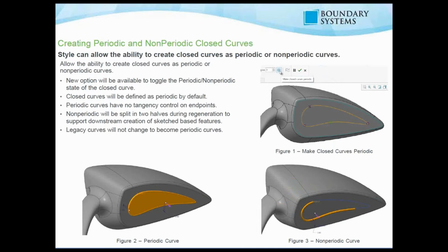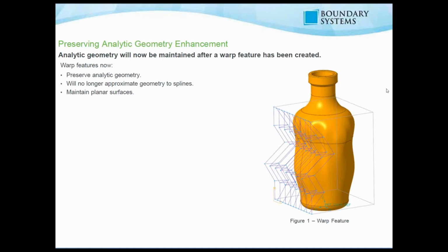Okay, so next is another thing with the style tool: periodic and non-periodic closed curves. Style now allows the ability to create closed curves as periodic or non-periodic curves. The closed curves will be defined as periodic by default and have no tangency control on endpoints.